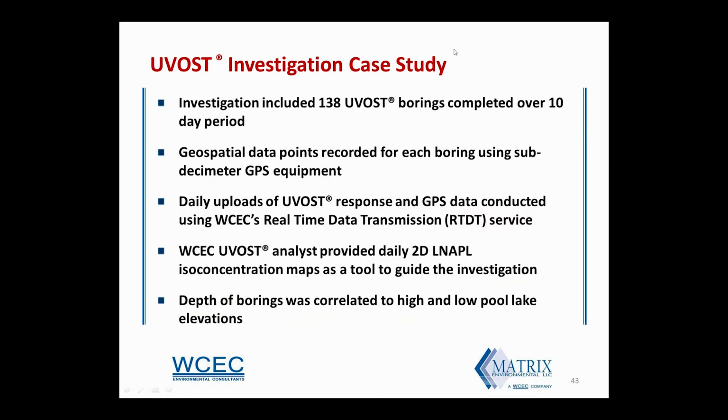There we go. So this investigation included 138 UVOST borings completed over a 10-day period. So when you worked out the numbers, we were getting about 500 feet a day. This is a pretty ideal site for the UVOST equipment. We recorded geospatial data points for each boring using a sub-decimeter GPS. So we had XYZ data for all of our boreholes.